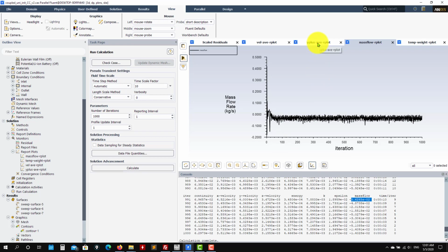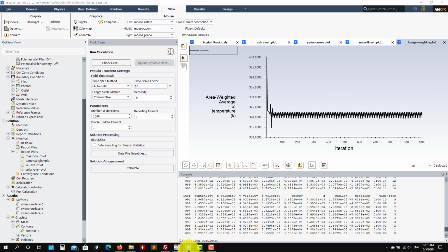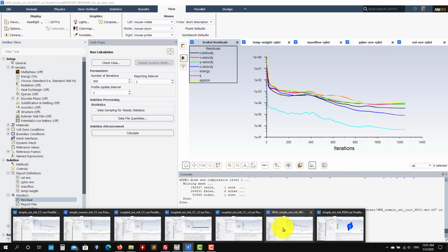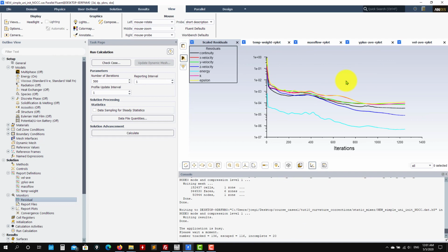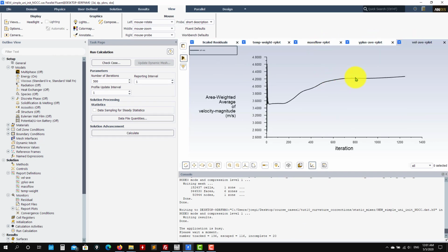And we know that this kind of approach is pseudo-transient. There is a big violation of many physical principles, because we're advancing the solution using this local time step approach. It works, but when you choose wrong parameters, it has the tendency not to conserve. And then we keep looking here. So we have the solution we just ran. See that we have everything. So here might be an indication that you need to run a little bit more. See that it's oscillating. See that in the other cases, the couple is kind of converging at 4.5.